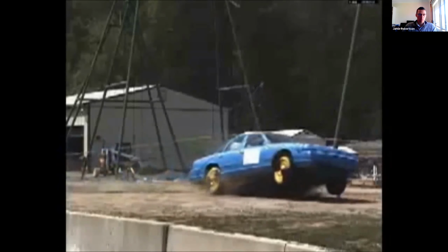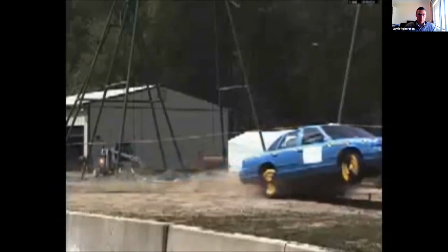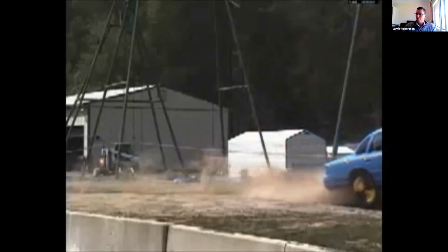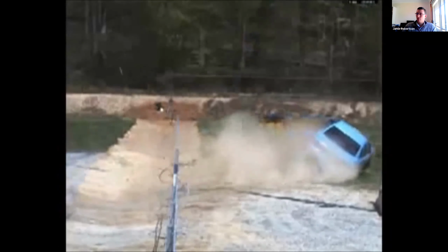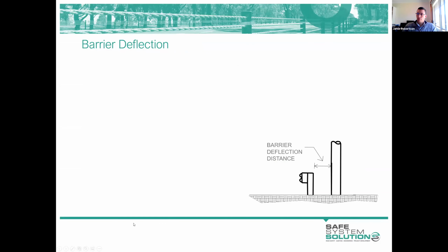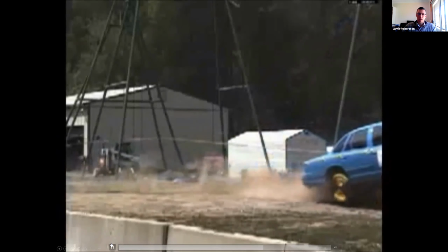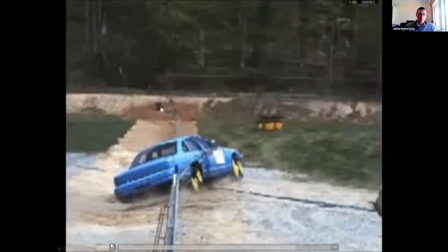Another video, and this vehicle obviously has penetrated that barrier. I wonder why. This view shows it a bit better. We've got a table drain there with a barrier located just beyond the invert or perhaps a metre behind the drain. If we look again, you'll see that when the vehicle passes through the drain, the bumper height goes down as the suspension kicks in and the vehicle noses under the system.